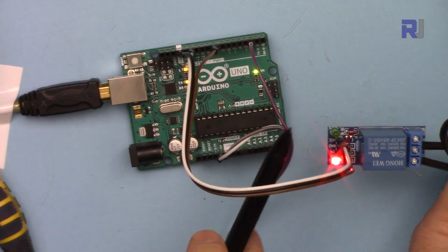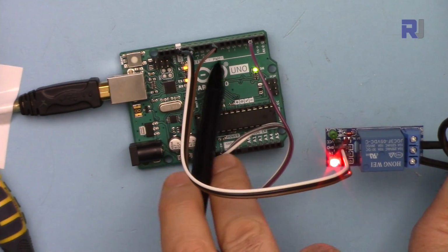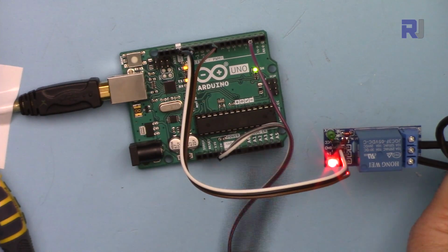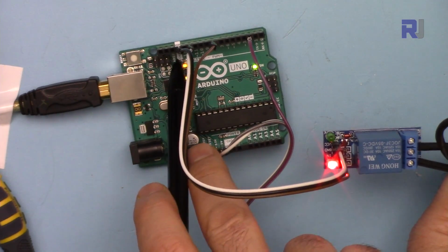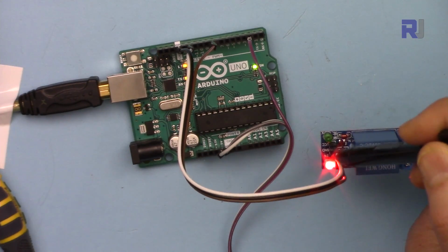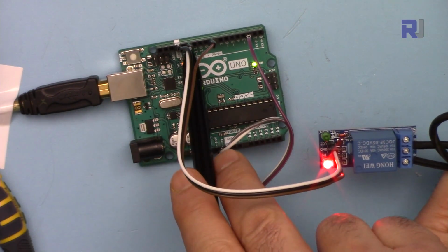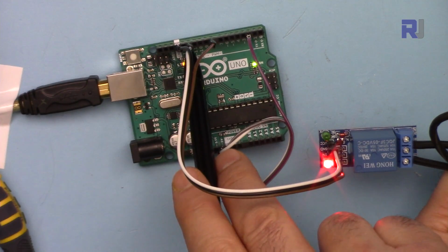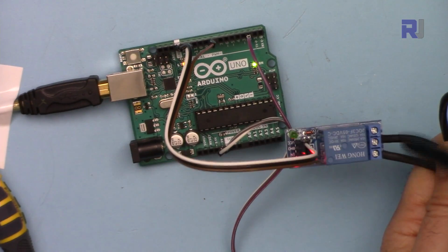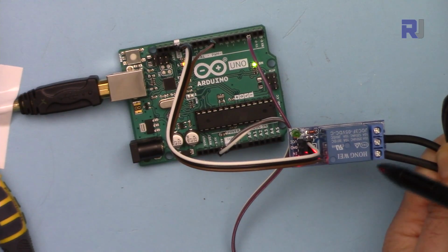For the relay, the right pin is IN. This has been connected using a brown wire to pin 8. The middle pin is ground, connected using this black wire to the ground of the Arduino in here. And the last pin on this side is VCC, connected using a white wire to pin 12, which has been defined in code as VCC2 or extra 5 volts for this relay. The 2 wires of the bulb have been connected to these 2 pins of the relay, which have been explained before.